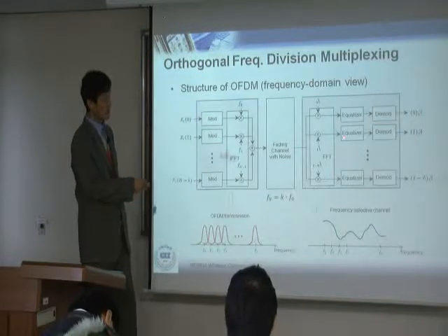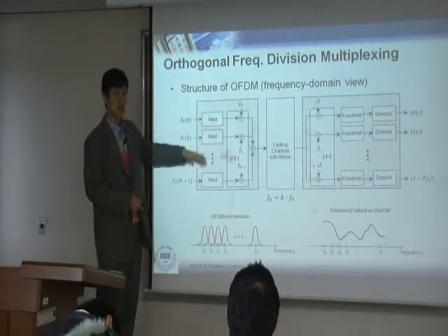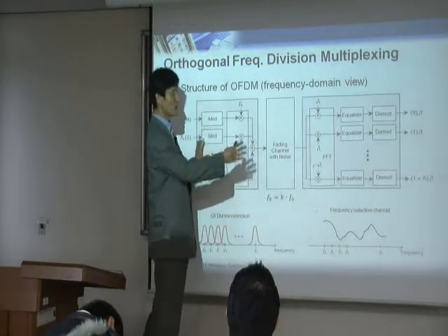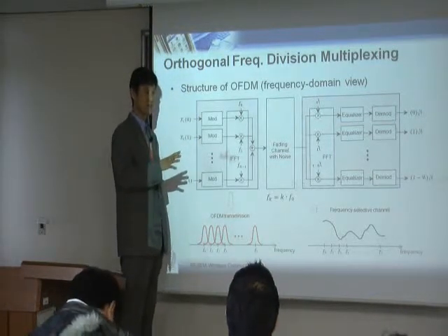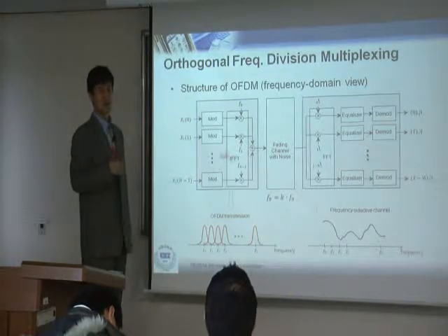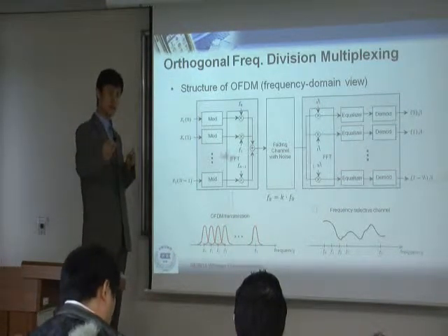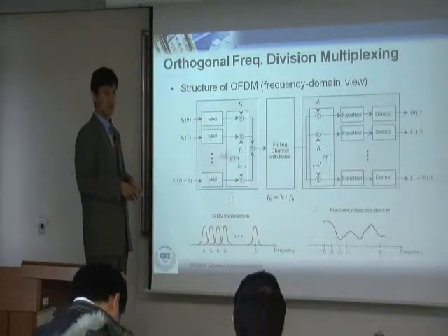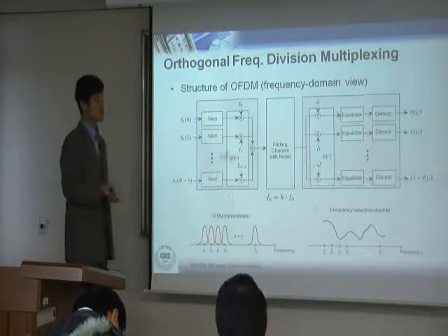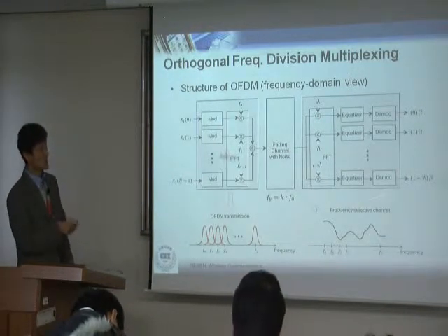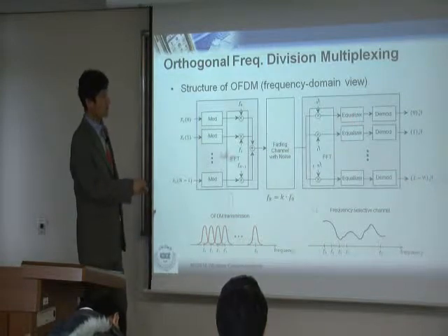And this is another reason: in OFDM, you can use independent modulation for each frequency. These two nice features are the fundamental reason why ADSL technology is popular, not the telephone modem. No one uses a telephone modem these days. With the same telephone wire, everyone uses ADSL. Why is that? Because the telephone modem uses a very complex equalizer, and even then you cannot exceed 56 kbps. With the same telephone wire, using this technology, you can achieve several Mbps. So the equalizer is very simple in OFDM.